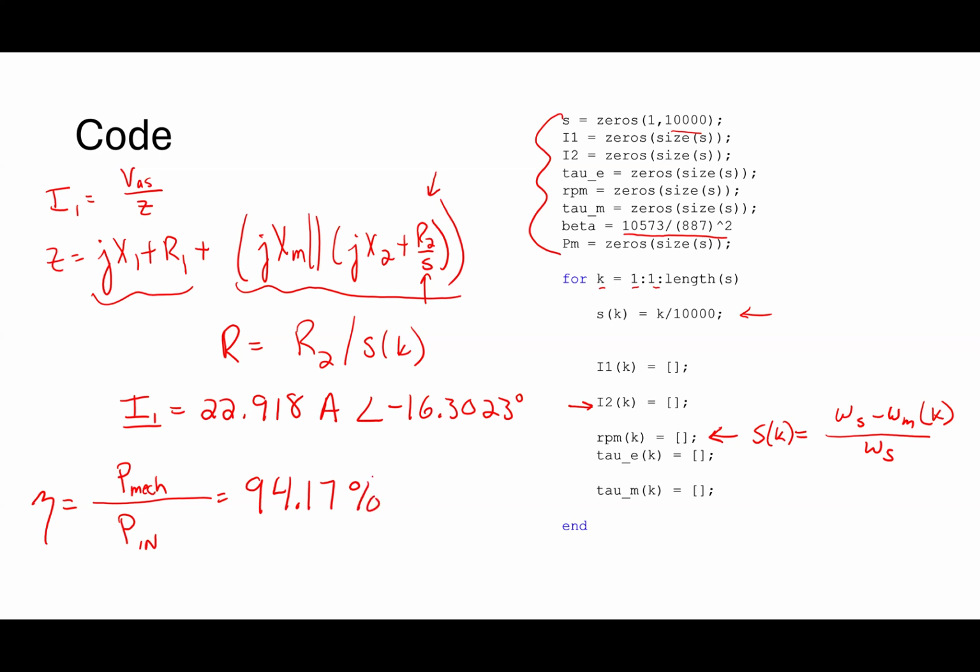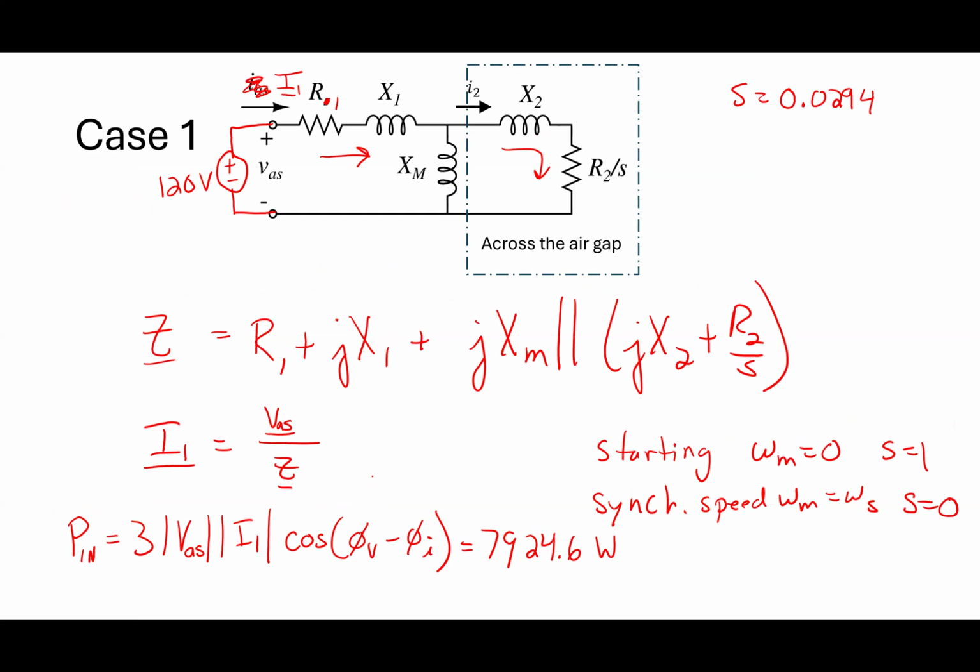That's pretty typical for a lot of motors. It's somewhere 94, 95%. In other words, about 6% of the input energy becomes heat. If you go into a plant and you touch a motor, it will feel warm. Because we're talking about 6% of 7.9 kilowatts. What's 1% of 7.9? 1% of this would be what, 79 watts, right?